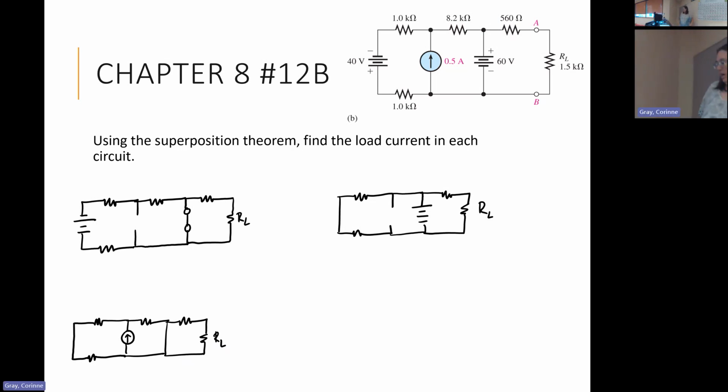So let's go ahead and focus on our first situation here, which corresponds to the left battery. With this, I'm going to start here at my positive. I'm going to go down, go through a resistor. No current flows up because it's incomplete here, so nothing interesting happens. I get to this junction here, and which path has the least resistance? Yeah, this one has no resistance, so all of the current is going to flow up through this wire here.